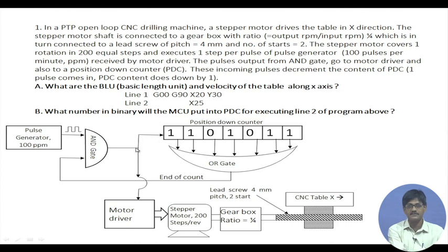These pulses are also being sent to the stepper motor. When you have sent the required number of pulses to the stepper motor, this should stop. So, those many pulses counted in binary should be put here, so that they are decremented and consequently further pulses will be stopped.